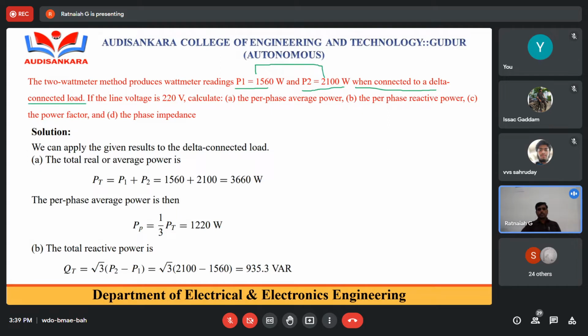Just please remember that here the 2-wattmeter method is applicable to either a star connected network or a delta connected network. It may be balanced or it may be unbalanced. So don't worry about it. The analysis carried out for star connection is the same as for delta connection. There is no doubt.